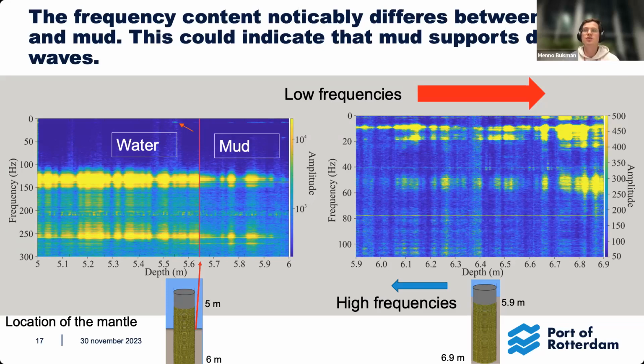Now, this could be related to a coupling effect. As you can see over here, I've highlighted a small anomaly with a red arrow. And this is where we taped the fiber to the pole again. Here, during installation, the fiber broke. And due to the tape, the coupling was increased.